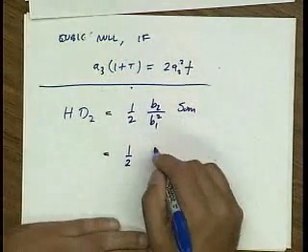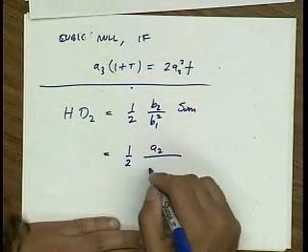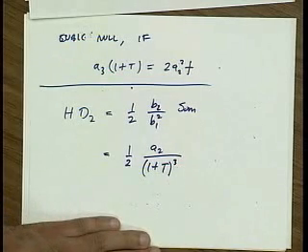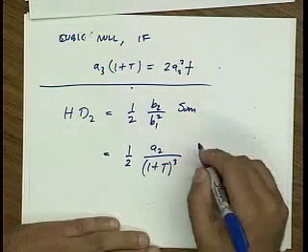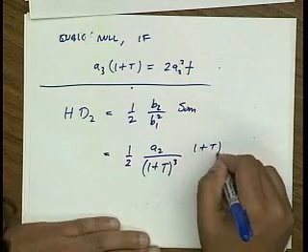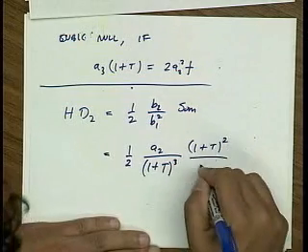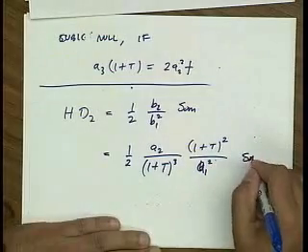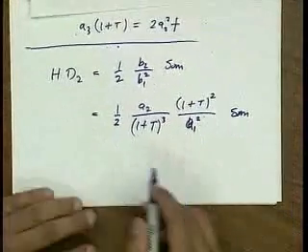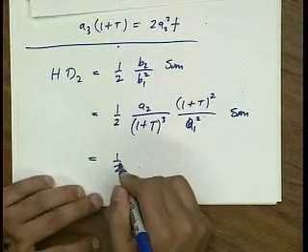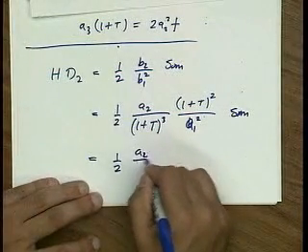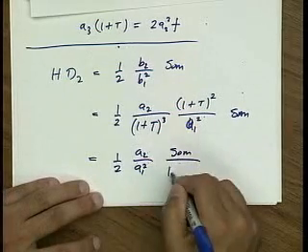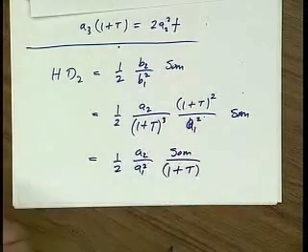So if I substitute, B2 I found is basically A2 reduced by the cube of 1 plus t. And B1, of course, is just reduced by 1 plus t. And so when all is said and done, I have that the distortion output referred is reduced by 1 plus t.